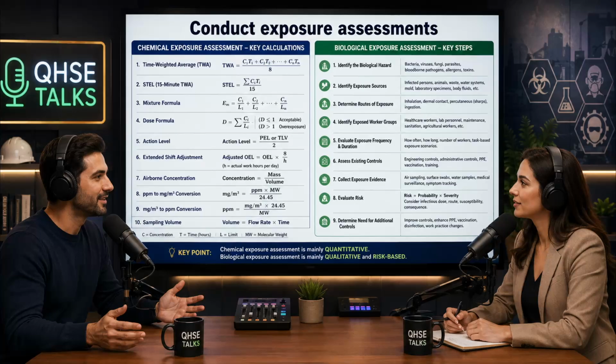That insight fundamentally changes how you view a factory floor. You can't just glance at a sound level meter, see it fluctuate from 90 to 95 and think, oh, it's just a bit noisier today. Not at all. You have instantly decimated the worker's protective timeline. You need immediate administrative controls to pull them out of that room.